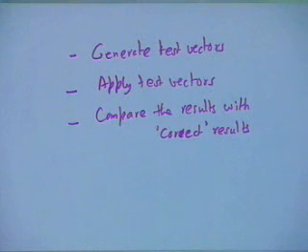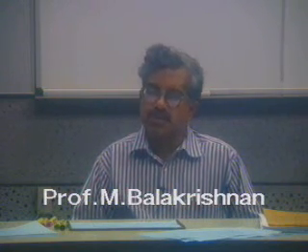If the circuit is very complex, your test patterns are going to be very large, and once your test patterns are large, you have to consider the storage that is required. One is storage required if you are storing it on chip. If you are storing externally, of course you can store it on disk, which is a fairly cheap medium to store today, but the time that will be required to test, because you have to transfer from the disk one by one. Similarly, if you have a large number of test vectors, you have a large number of results, and you have to read those results, so that's also a cumbersome process, and then compare with the expected results. Again, there is a lot of storage required. If you are going to do that on chip, then again the expected values have to be stored in a ROM and then compared.